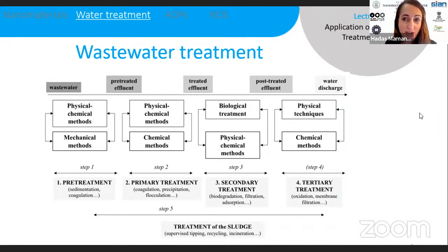So I would say that in most cases, the advanced oxidation process is the last step. When we have residual contaminants in the waters, such as pharmaceuticals, drugs, personal care products, pesticides, herbicides, and these types of organic chemicals that cannot be oxidized through the standard biological treatment, which is not intended to remove those pollutants. Also, it depends on what the next step of the effluent is.